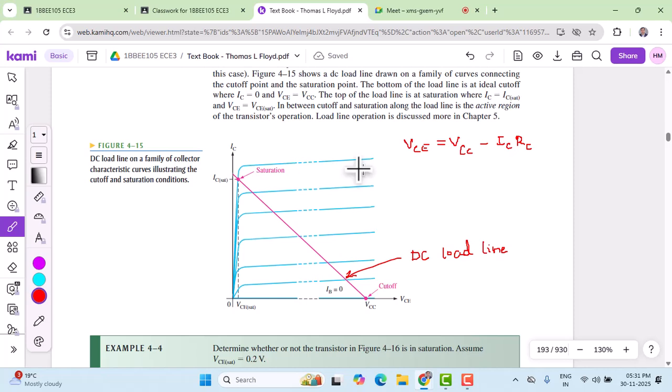This relation assumes that the collector emitter voltage is maximum, and from that we can estimate what the collector current must be. In another way, if IC is going to be maximum, if I assume the collector current is at maximum, then we can estimate the collector emitter voltage for safe operation so that it doesn't exceed the ratio PD max by IC. So these two relations play an important role in deciding where one should operate a transistor safely.